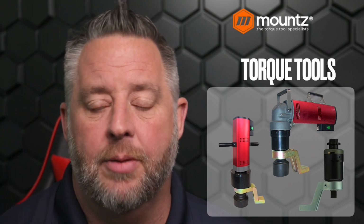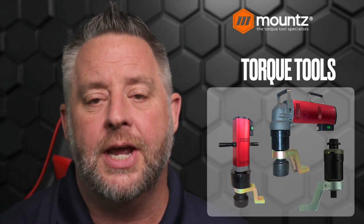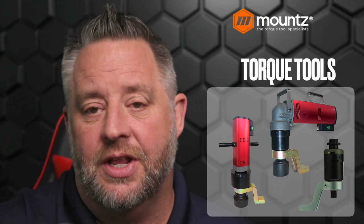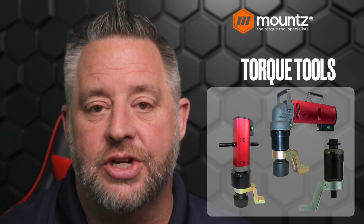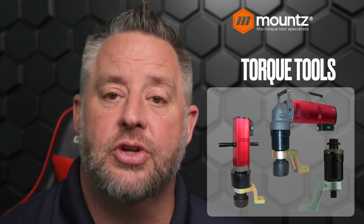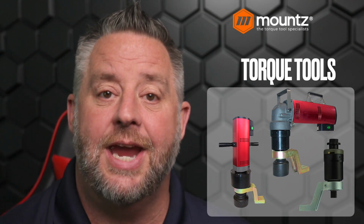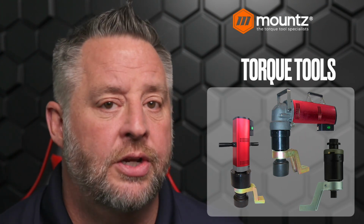And then the little reaction arm that you see coming off the tool there is what is actually helping to generate the torque value. So that is holding the tool stable as it is producing the amount of torque that we need. Once that input value is met, the tool shuts off and we've reached our torque value. This can be available in electric like this. We also have a pneumatic style that uses a stall motor and PSI to determine its torque output, or you can even use a hand multiplier, again, depending on if that is going to be a 4:1, 8:1, 12:1.